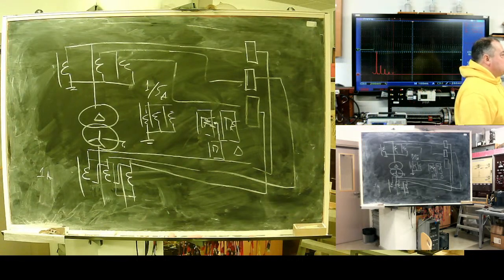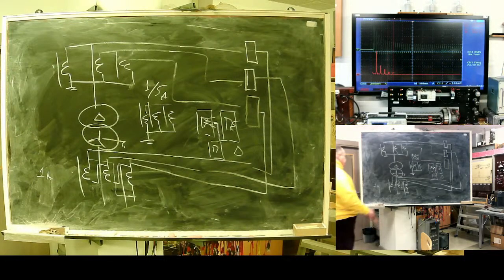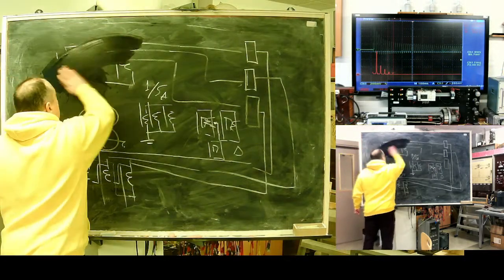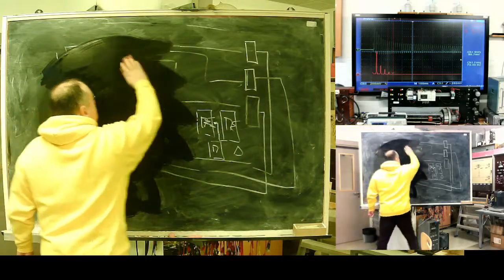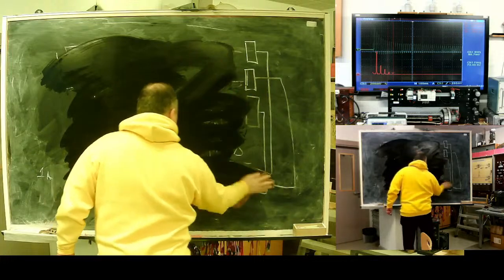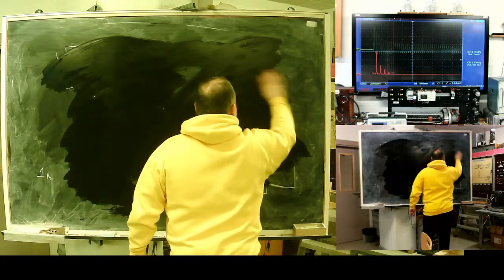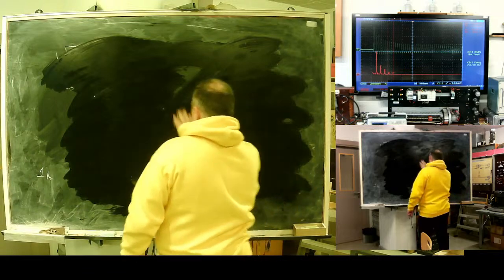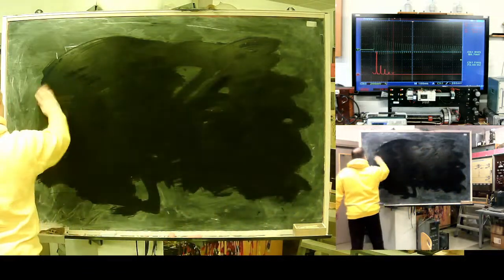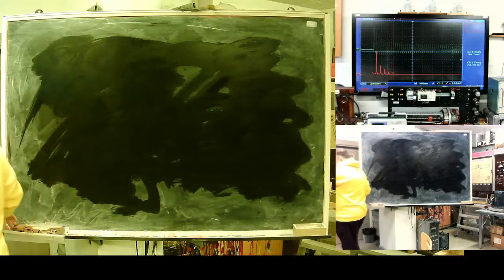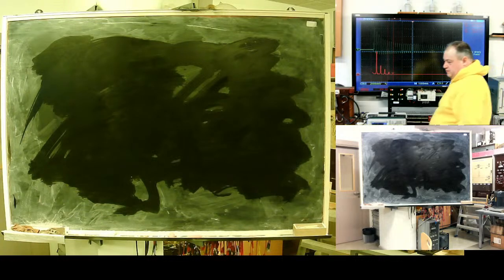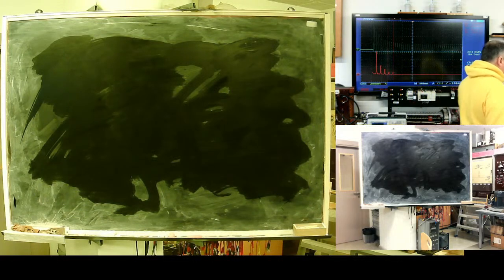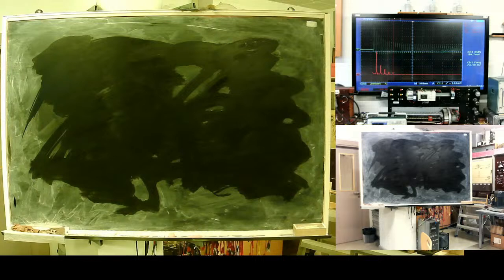You know when it appears? When there is no switch designated for the transformer. It's a cheaper design where the transformer and its output buses are one zone of differential protection. In such designs, these interim transformers appear. But nowadays it's done differently.